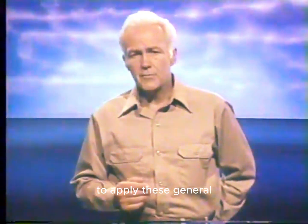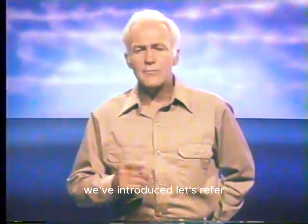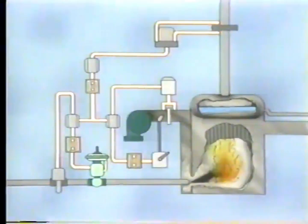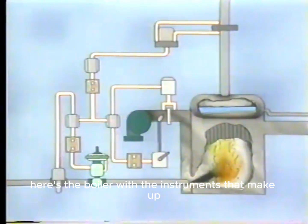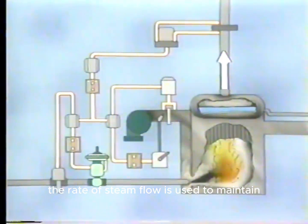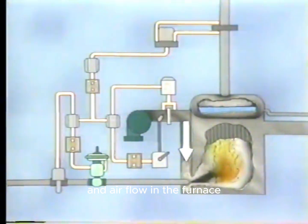To apply these general principles of cascade control to the boiler system we've introduced, let's refer once again to the illustration of the boiler. Here's the boiler with the instruments that make up the cascade control system. In this cascade system, the rate of steam flow is used to maintain the proper rate of fuel flow and air flow in the furnace.